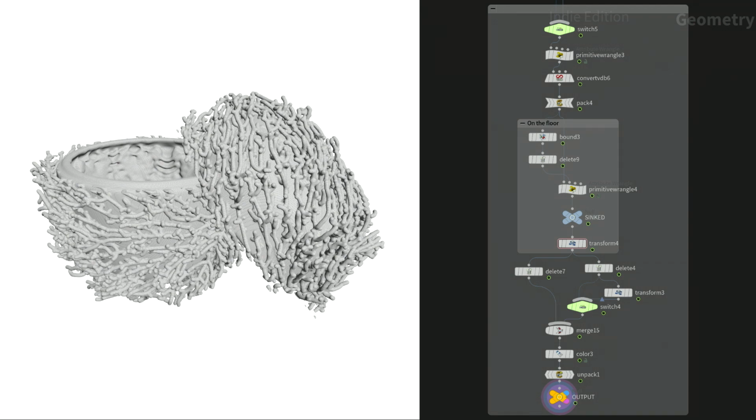So we wanted to first print this as a wax shape and then later cast metal into it. There are some constraints when you do that. You need to have at least 1 to 2 millimeters of thickness for each branch. So I had to make sure that each branch has this thickness and everything is also connected.